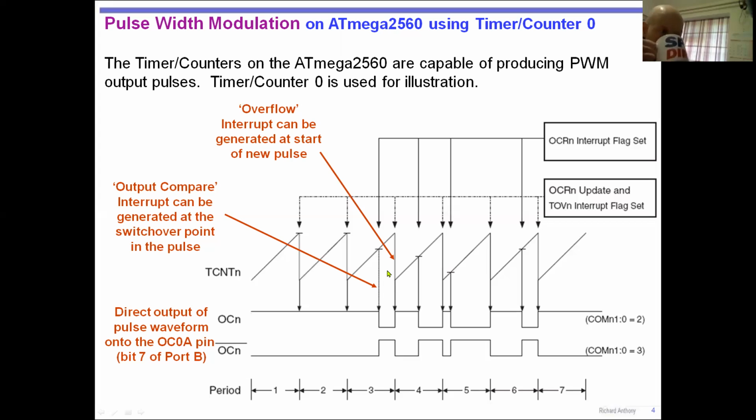Each PWM signal is calculated per period, because it might look like from this image that the first high, or sorry, first low is actually after 2.5 to 2.75 periods, but it's actually not the case, right? It's not 2.75 periods. It's the first two periods you're not doing anything.